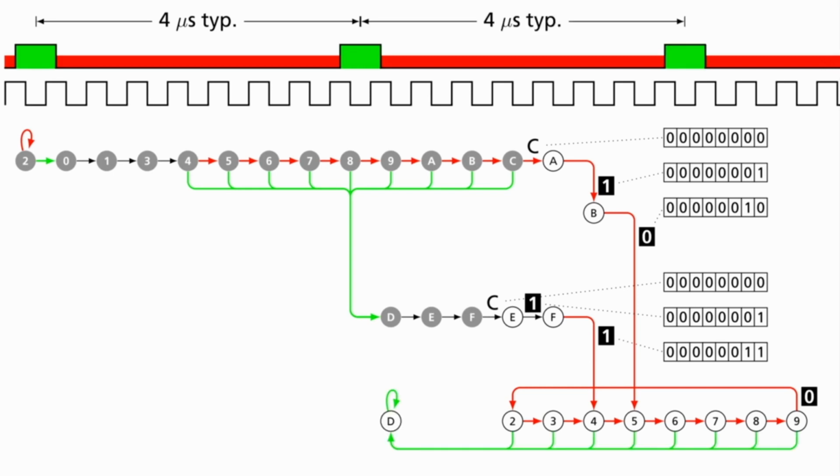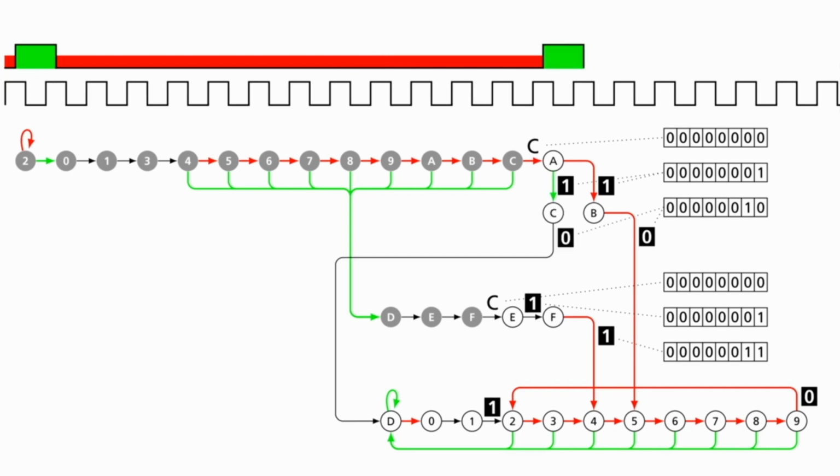Now, if a pulse is seen during this process, the sequencer immediately knows it saw a 1 and stops looking. Here I've drawn the pulse the usual 8 cycles after the previous one, but it isn't always exactly here. The sequencer then waits for the pulse to go away, which should happen immediately, waits 2 cycles, and then shifts the 1 it just saw and starts looking for the next bit. There are a few other corner cases. If a pulse occurs while we're shifting 1, 0, we need to remember it and shift out 1, 0, 1. Similarly, if we saw 2 1s at the start of the byte, an early third pulse could interrupt us.